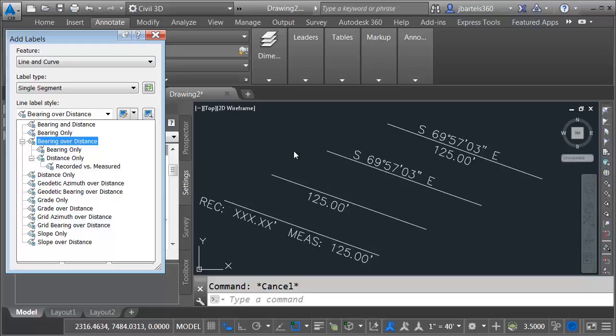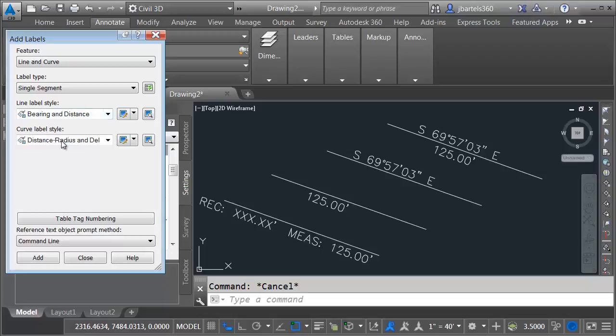The place where the child styles come in handy is if your label styles need to change. For instance, after creating these, maybe I realized they all have the wrong text height. Had I made these as separate styles, I'd have to edit all 4 of them separately. In this case, all I have to do is edit the parent, and those properties will pass down to the children.